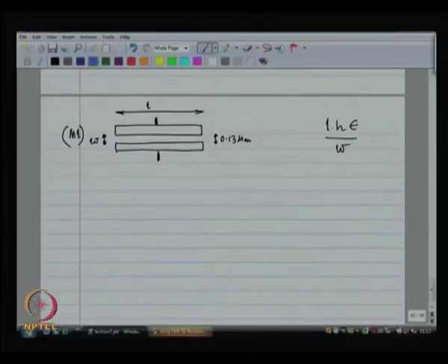So, there is going to be fringing over the top and underneath the bottom. Okay. Fringing is not bad, it just adds a component. As long as you know the height, you can compute out the fringe factor, the fuzz factor over there, and you can figure out for yourself what is going to be the capacitance value.